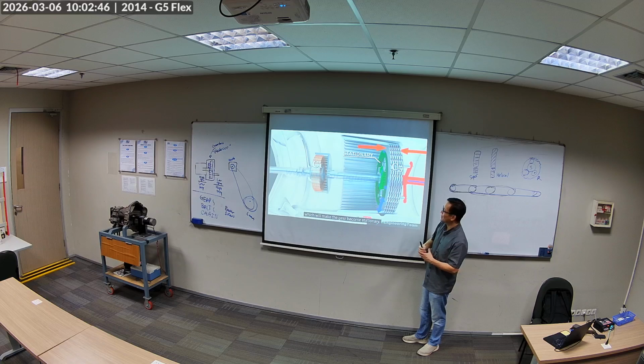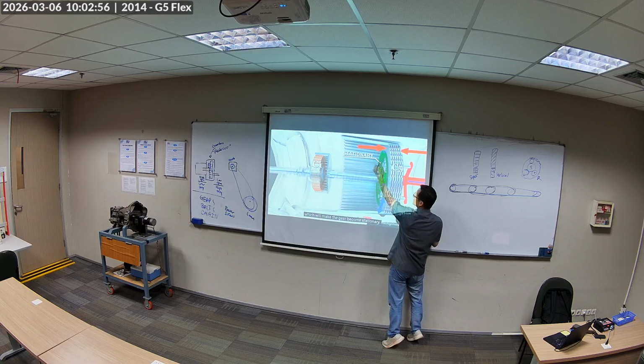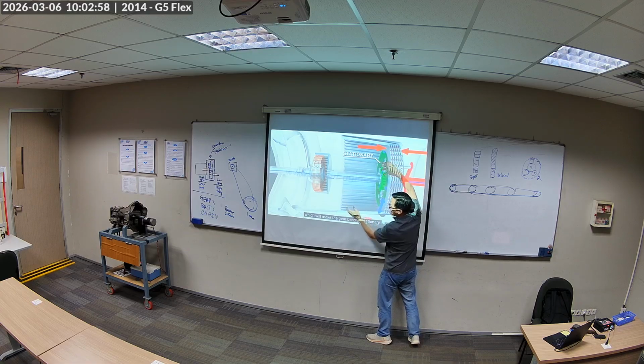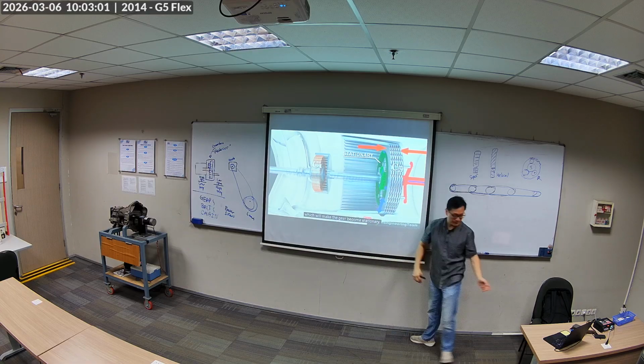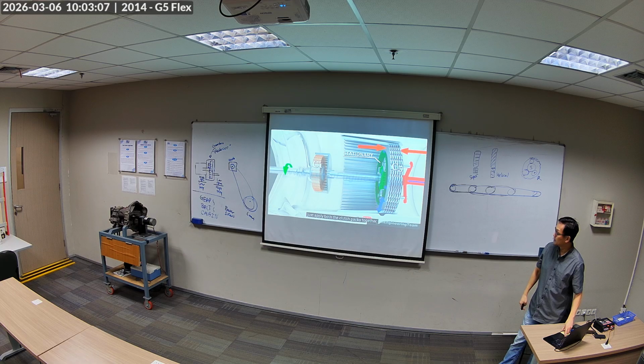There are more clutch packs coming up. But this is the same arrangement, okay? The gray plates and the bronze plates, they're packed together, and it can lock this ring to the case. This big one is a case. In order to achieve the first gear, just apply both the clutch packs together. You can note that the input shaft will turn the sun gear.